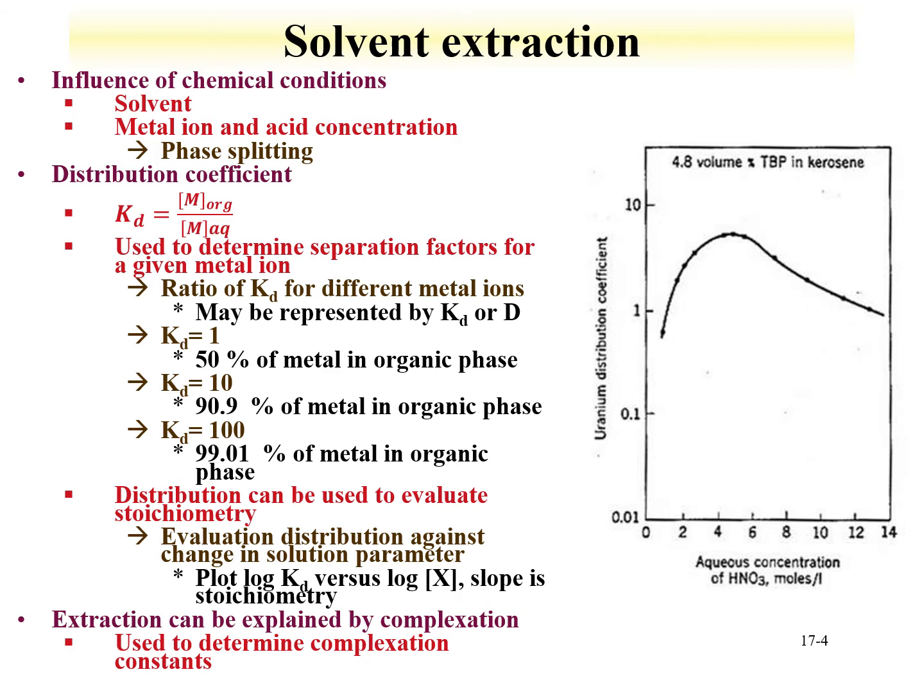For solvent extraction, we can vary solvent conditions, for instance, changing the concentration of tributyl phosphate in kerosene. We could also vary the ligand. We could have other ligands in the system. We can have two ligands for a synergistic type extraction. Or the aqueous phase can be varied. This can include changing the acid concentration, which influences the metal ion. We've already discussed oxidation states. One can also add other counter anions, such as using a nitrate salt to increase the nitrate concentration.